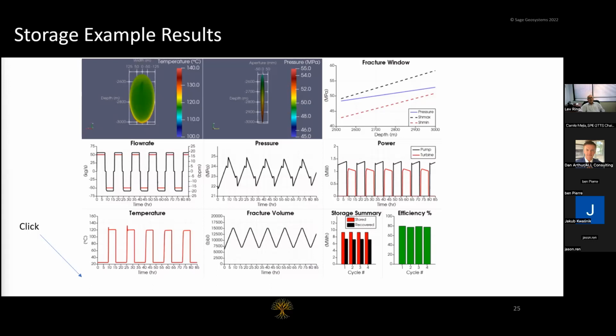I keep it always pressurized, okay, above fracture closure. I never allow this fracture to close. And so I operate between fracture opening and fracture propagation pressure, and it allows me to maintain the desired temperature when I need it. It heats very fast. Yeah, it takes time for fluid to replace the well volume, but it may take 15, 20 minutes to do it.